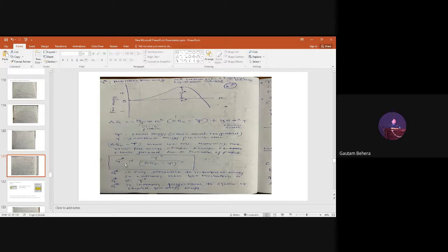G star will mainly depend upon this term, the gamma cube term, yes or no? The interfacial energy term is more important now. More is the interfacial area, more is the interfacial energy, right? So here it is written, G star is very sensitive to the interfacial energy because it is gamma to the power cube. Gamma here means your interfacial energy.